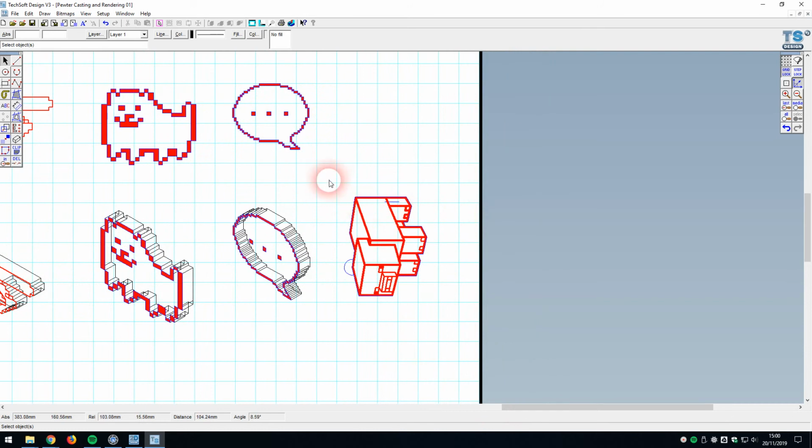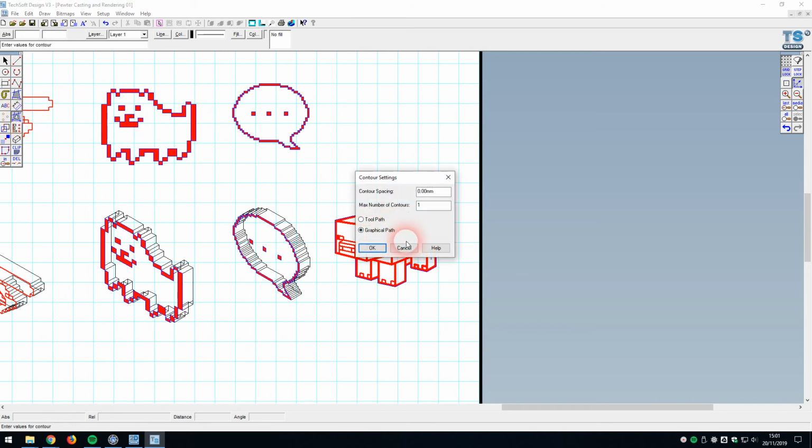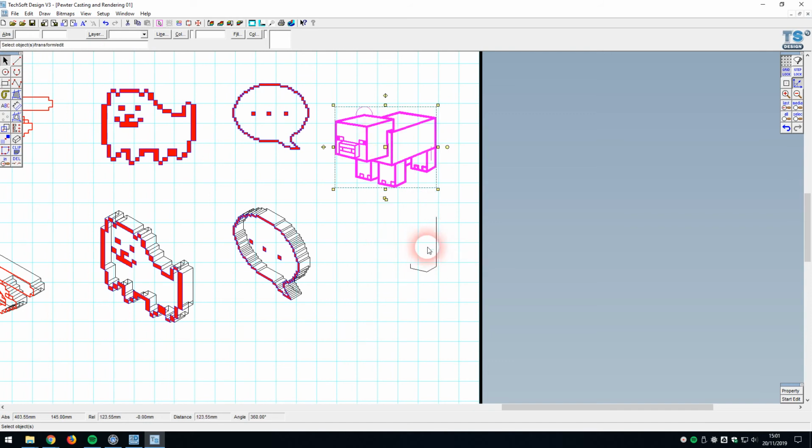How is he going to work out? I think this one has a problem. First of all, I've got to rotate it. So I've got radio locked on here, which is going to allow me to just rotate that through 90 degrees. And here, I think, lies the problem. If I go to contour tool and I click on this, what happens is that contour, where's the contour? Yeah, the contour just does that.